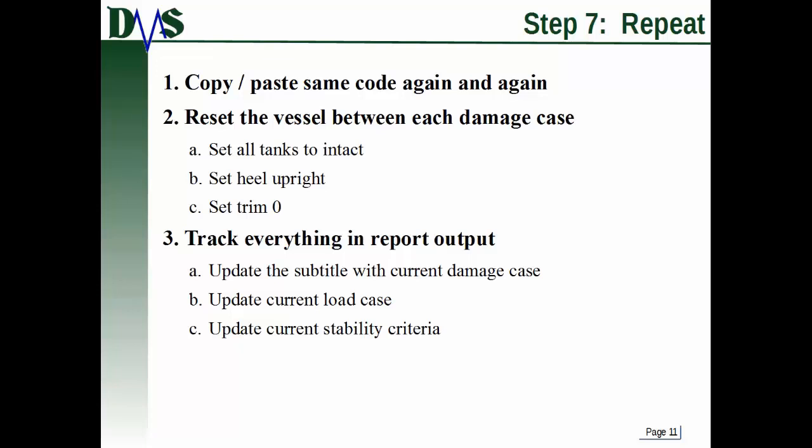Now, the reason for all of that is that you might have some damage cases that cause the vessel to completely flip over. That makes it very hard for GHS to recover from a flipped over condition to re-equalize. So you just want to tell GHS to reset it to the correct heel. And it just gives you a good stable point to start from every time.